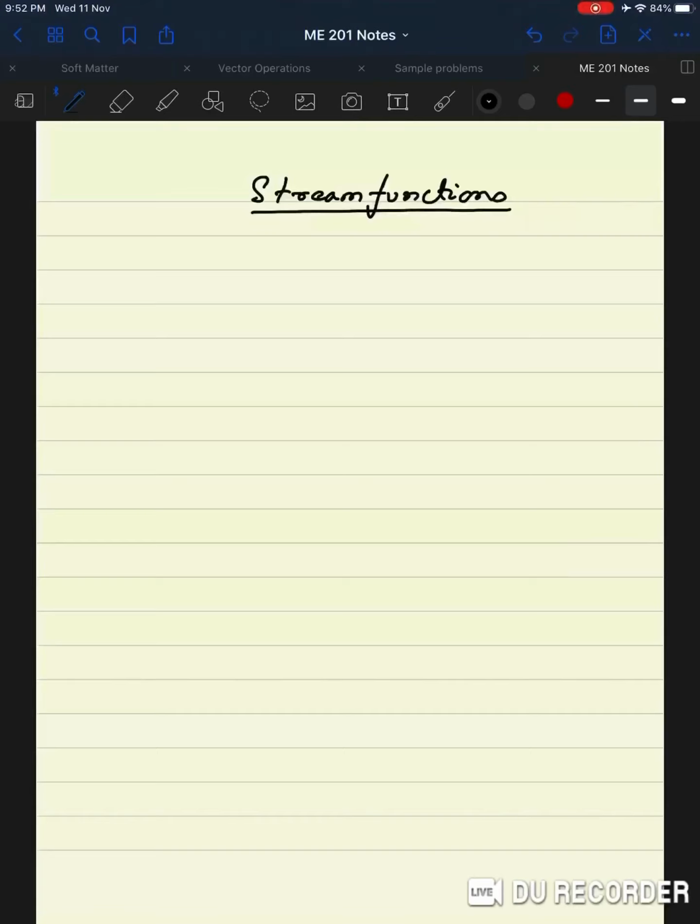And these are for 2D flows, and it satisfies the continuity equation, and we want to show you the stream function is constant along a streamline. Okay, and that's a very important observation. And the flow doesn't have to be axisymmetric, you don't have to do it in Cartesian coordinate systems, but you can also define the stream function in, let's say, polar coordinates.